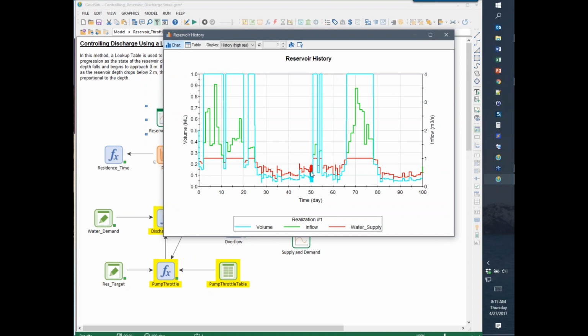You see there's a little bit right over here, but you can see that it looks much better, right? And the reason for that is because we are updating calculations on such a small time step that we're able to not overcompensate when we say, okay, withdraw some amount. It will only do it for a short amount of time. Therefore, it's not as much water going in over the time step, right? Because it's a small time step. So this is one way to deal with it.